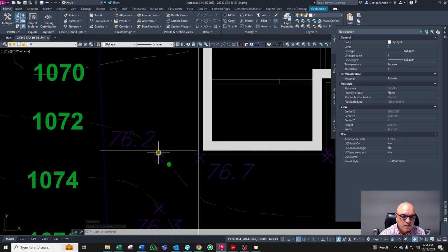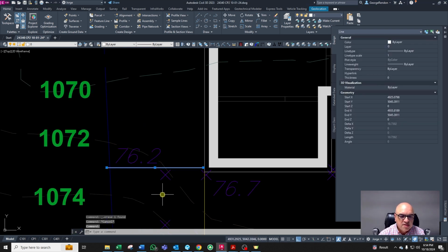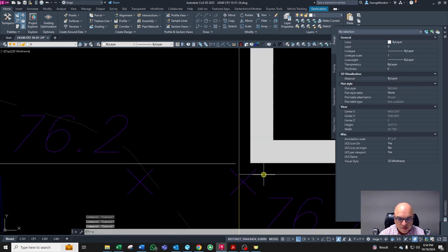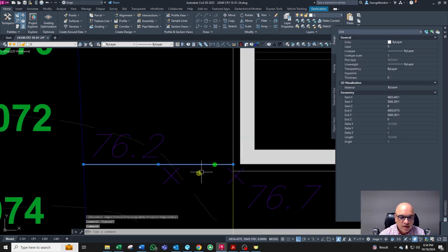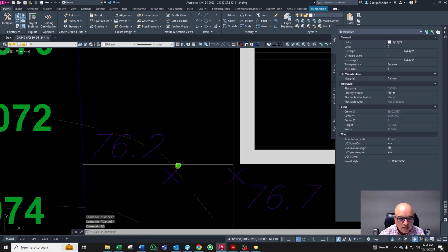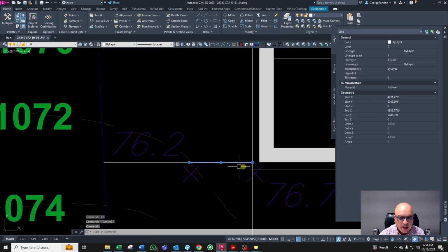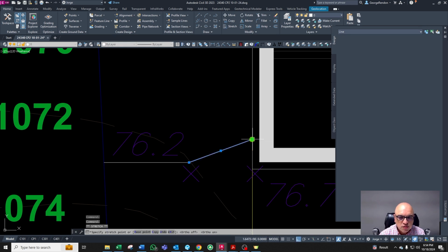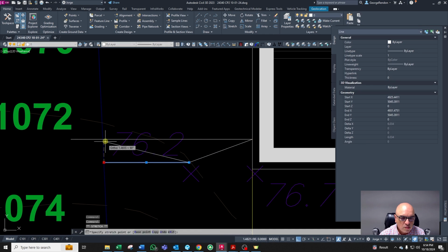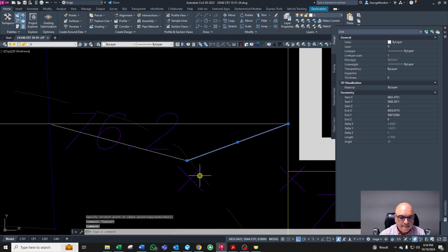So it's 8 feet. Now, basically what happens is I'm going to create like this swale in the middle between the house and the property line. I'm going to break this line right here, and I'm going to create again water away from the house, and I want my bottom of this swale to be 2 feet wide.